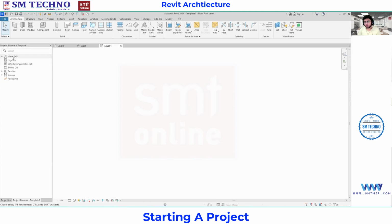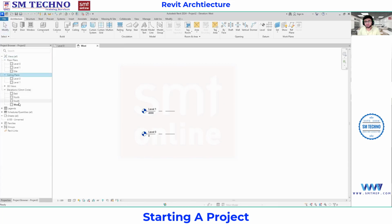You can see there is no elevation view. There is nothing like floor plan over here. We need to create them because we have selected none. If you select none, we need to create all the files. So by default, without any waste of time, we are going with the basic template which is given by Revit, where you can see by default you have some floor plans, some ceiling plans over here, and some elevation views. If you work with any consultancy, by default, you are going to find a few more tabs where they will define the sheet, the floor levels, grids, everything they will specify.